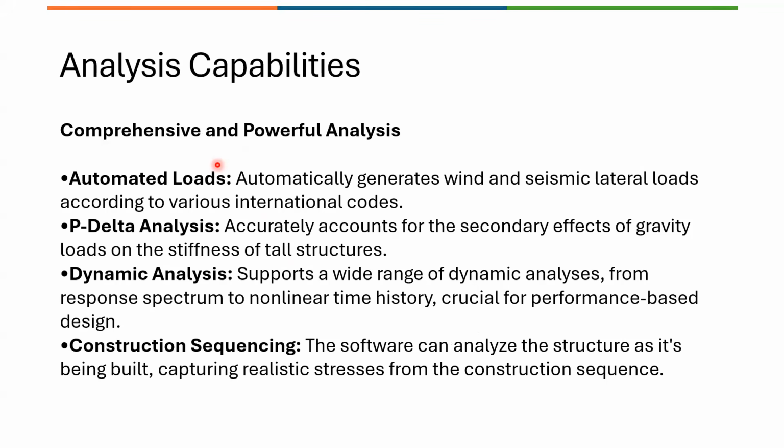And then we are going to analyze the structure. We have comprehensive and powerful analysis tools, starting from the loading: we have automated seismic loading and wind loading based on various international codes, including Indian codes. For geometric nonlinearity, we have P-delta analysis. For material nonlinearity, we can consider it in the analysis through the load case we'll set up.